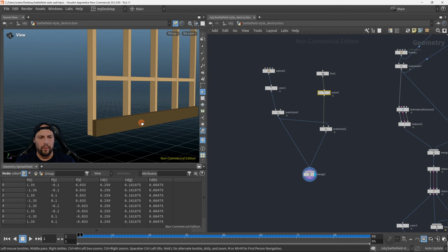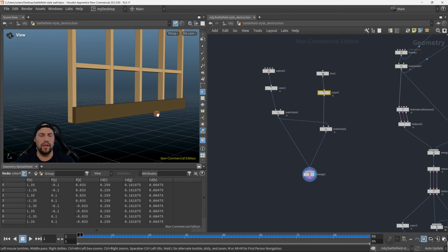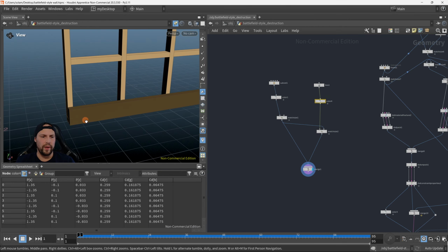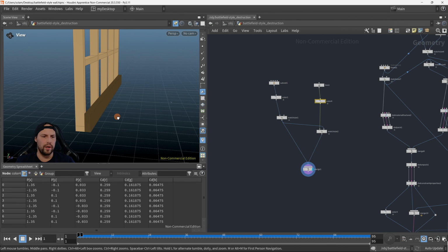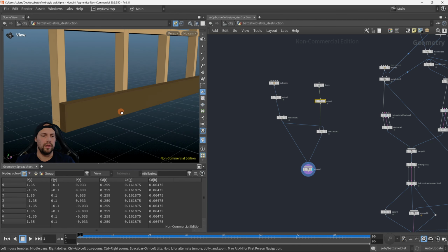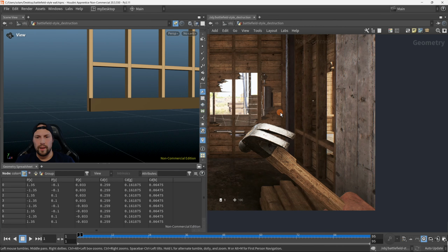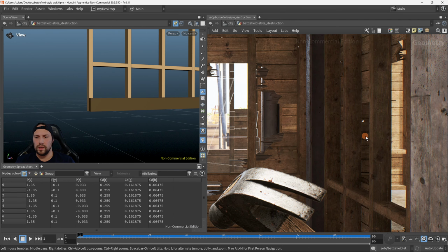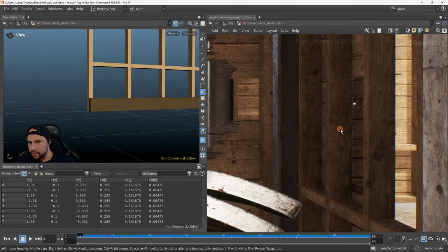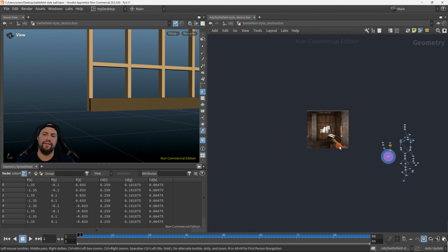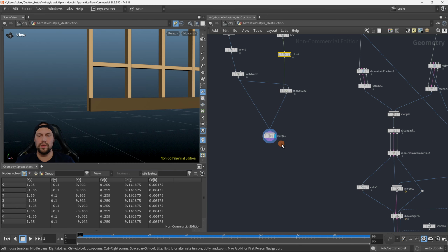What if we try to give this plank a little bit of a bevel? Because right now we have these edges that are super sharp, right? If we look at it, it doesn't really give us any highlights or anything. If we look here, I think it might have a little bit of bending, but that might be faked with normals or weighted normals.